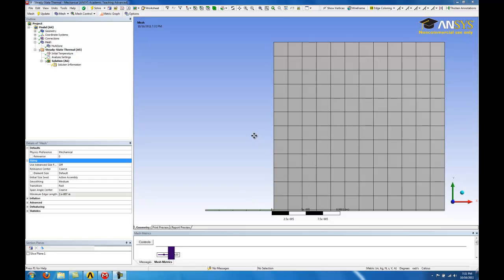In order to see that your mesh is actually a correct mesh for the geometry and simulation that you're using, you should always refine it. Make the elements smaller and see if the results from the past mesh, the coarse one, and this new one, the fine one, converge onto a solid figure. If they do not, it means you need to keep refining until it does. Otherwise, your simulation will be non-applicable to anything. It won't work. It'll just give you gibberish.